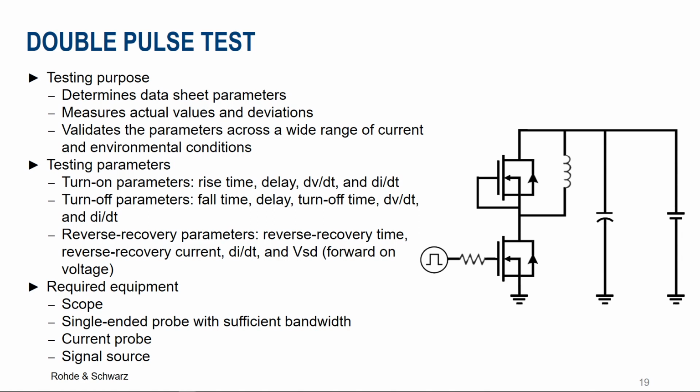So for turn on, the rise time, delay, dV/dt and dI/dt. For turn off, the fall time, the delay, and the turn off time, and dI/dt and dV/dt. And the reverse recovery parameters, which would be the reverse recovery time, reverse recovery current, dI/dt, and VDS.